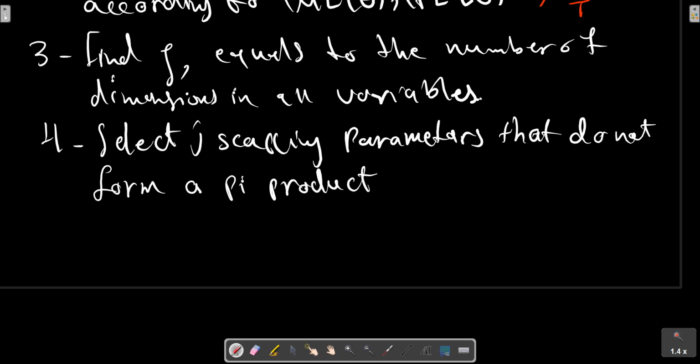Make sure they please you and have some generality if possible, because they will then appear in every one of your pi groups. Pick density or velocity or length, for example. Do not pick surface tension, for example, or you will form 6 different independent Weber number parameters and truthfully annoy your colleagues.